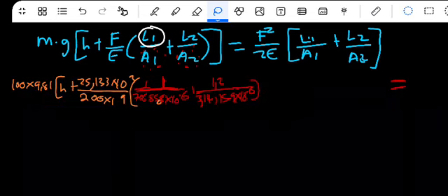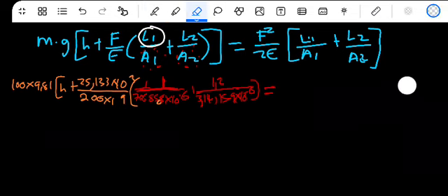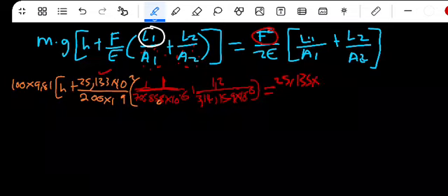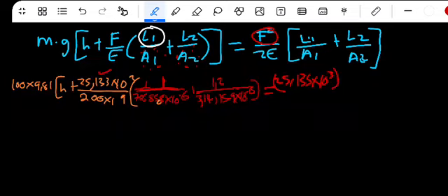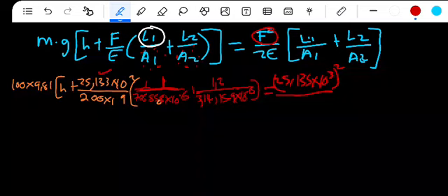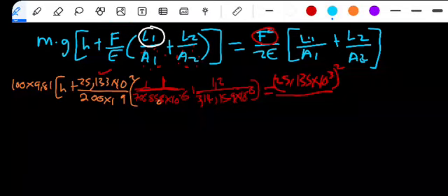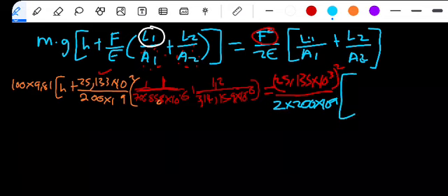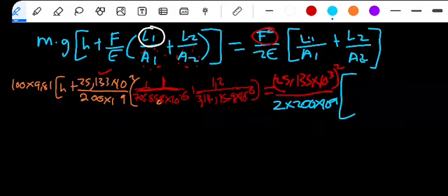Right, that is what we have. This would be equal to force squared there. We have our force, it was this one, 25,133 times 10 to the power of positive 3. We square it, since you have a square, divide this by 2, multiply by Young's modulus of elasticity, which is 200 times 10 to the power of 9, into length 1 and area 1. So length 1,